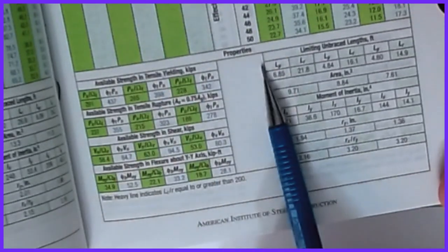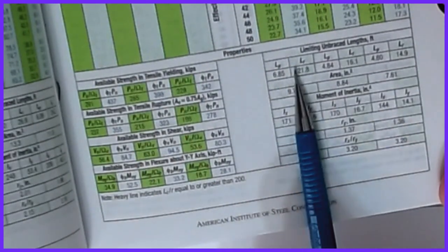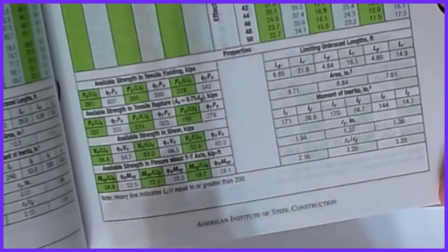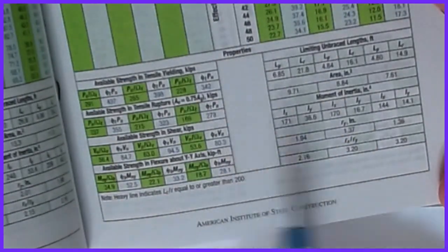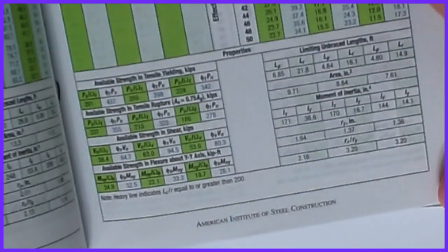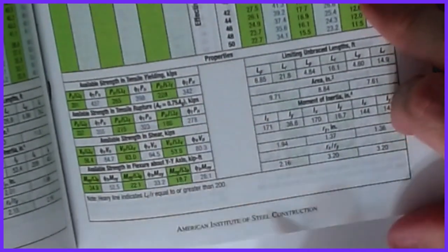But you also get a bunch of other section properties that you saw in the column tables and even the ZX tables. Here's LP, here's LR, here's IX, here's IY, which are your moments of inertia, all things that you need to be able to calculate this next step. So these are nice tables because they have everything in one spot. Now, all this information is duplicated over in Section 3 and Section 4, but you'd have to bounce back and forth between them, and it's nice having them all piled together in one. So this is pretty handy.